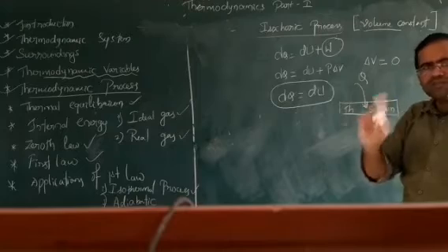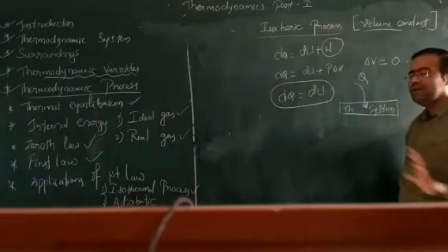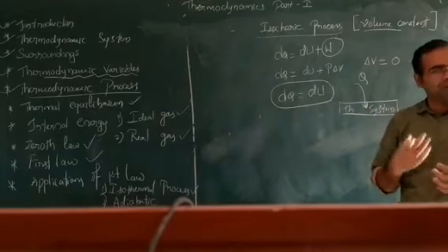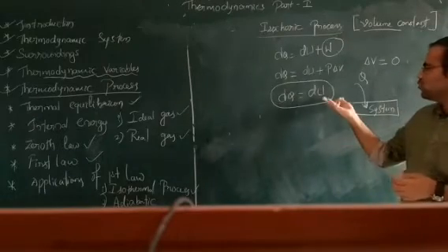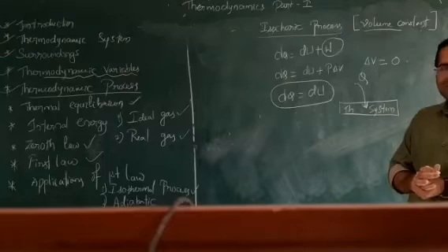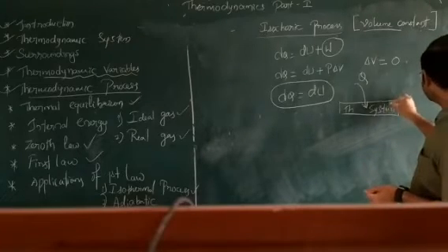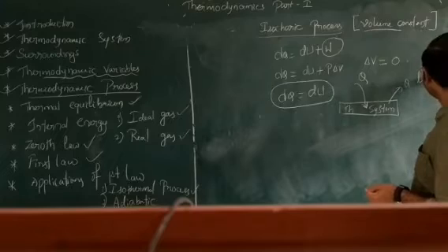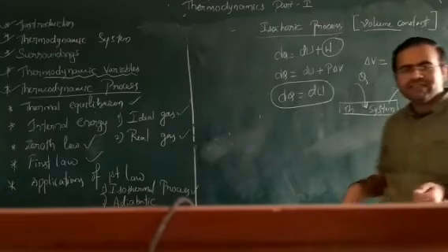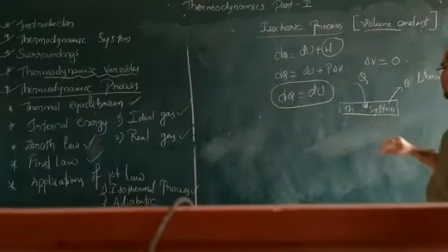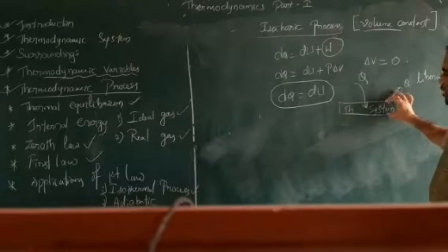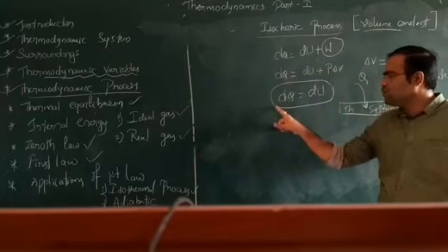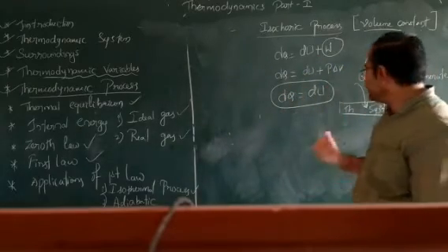this process takes place when we consider the isochoric process. So isochoric means whatever amount of heat energy you provide is used for the internal energy. Now if a certain amount of heat energy is liberated from this system, then the same amount of internal energy changes, and that is the heat energy liberated that you observe.